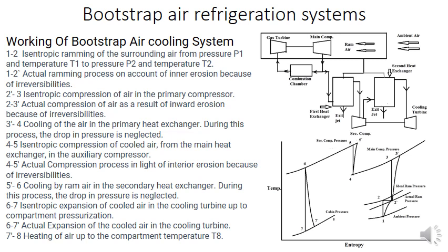The system consists of two heat exchangers, an air cooler and an after cooler. It also incorporates a secondary compressor which is driven by the turbine of the cooling system. This system is suitable for high-speed aircraft, where the velocity of the aircraft provides the necessary airflow for the heat exchangers. A separate fan is not required, because it is not suitable for ground running condition.